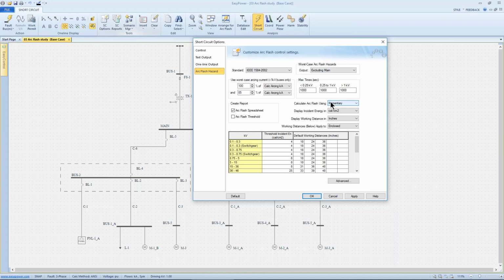However, if we have an extended trip time that lasts multiple cycles, that designation would actually give us an elevated incident energy calculation, because the momentary current was used to integrate over the full time of the trip unit, the last unit to trip.